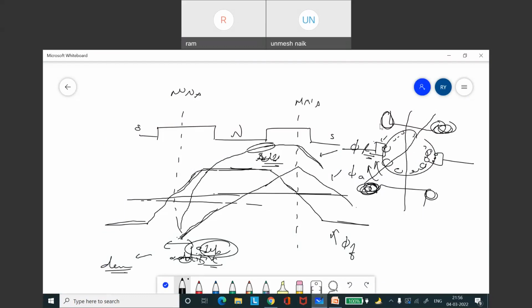If it comes later, it is called the trailing tip. Generally it's not important. Just remember that because of the cross magnetizing effect, the magnetic neutral axis position will change, which results in sparking at the commutator surface.